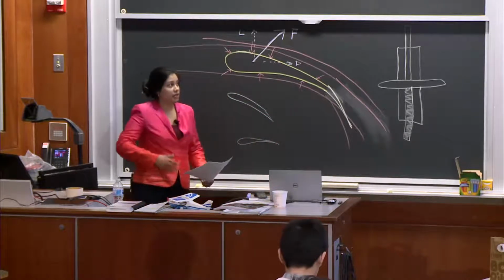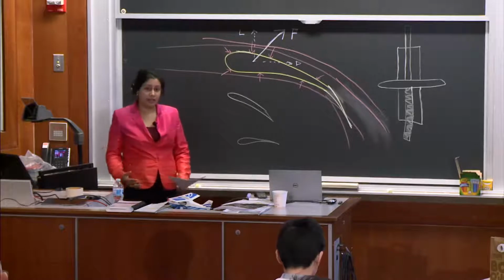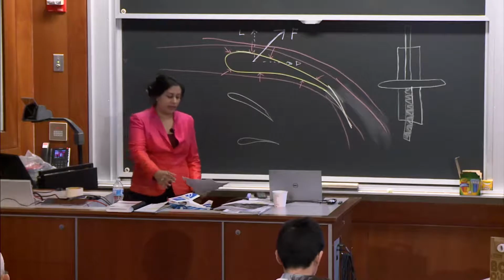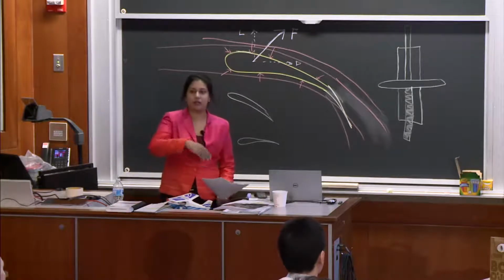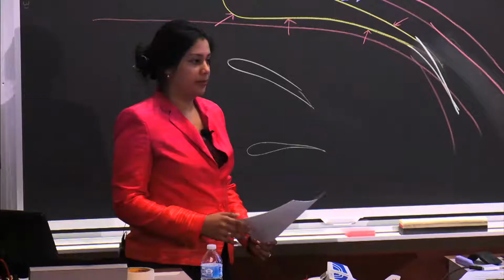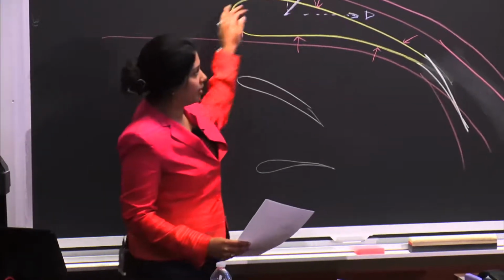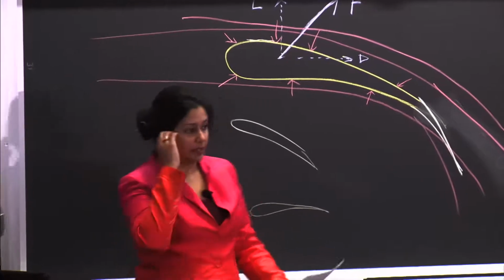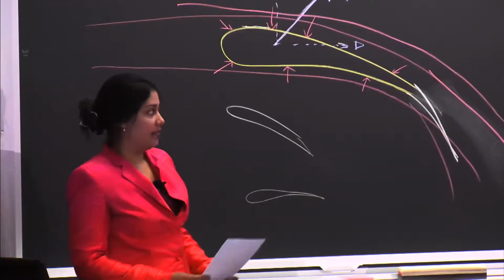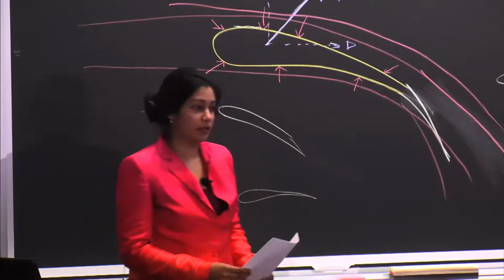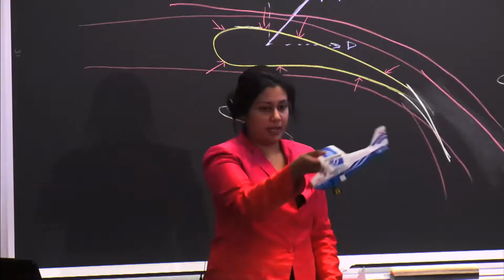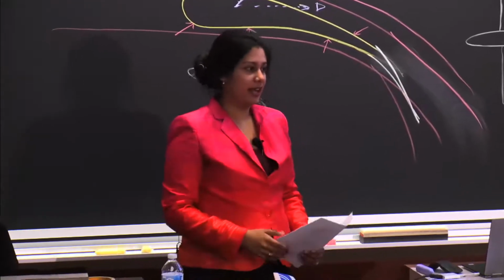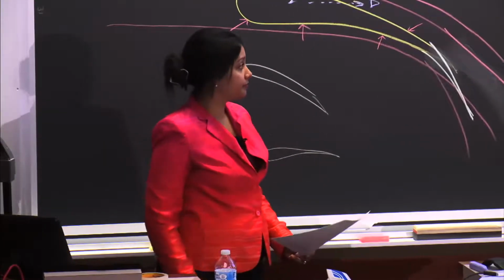Okay. So talking about how we can control the lift, some of the things we can do have to do with the aircraft design. We can build an airfoil, and we can decide how curved that airfoil is, the curvature on the top. We can design the wing area. When we're flying, we can control the airspeed. And then the angle of attack is something that you can control when you're in the airplane by pitching down or pitching up. And we'll describe pitching and how you control an airplane in more detail.